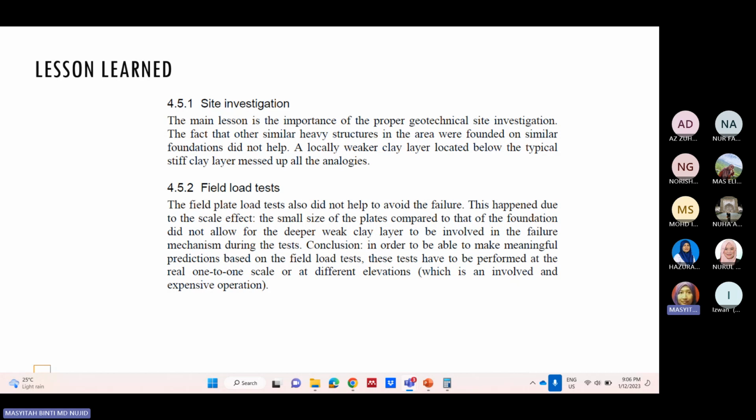So if you can carry out the shear strength parameter test, in the case of constructions on soft soil, it is better to also have a set of one dimensional testing results. From there we can get the compression index, then we can know the pre-consolidation pressure, we can know the OCR. OCR is a ratio that tells you whether your soft clay has achieved the strength required or has not achieved the strength we are looking for.